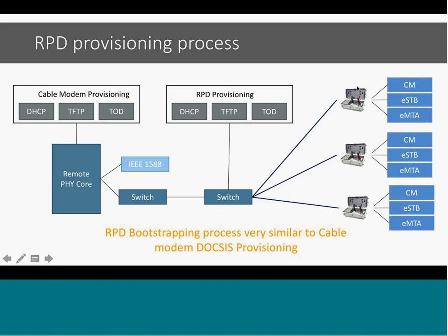Well, both my nodes do it the same way. The same. Cable Labs, again, they made it simple. They kept the same process that you're used to. So, you plug in this node. The first thing it does is go and get an IP address. So once it has an IP address, it goes out and looks to where its config file may live, and there might be a firmware, just like a .cm file. It'll be a little different.